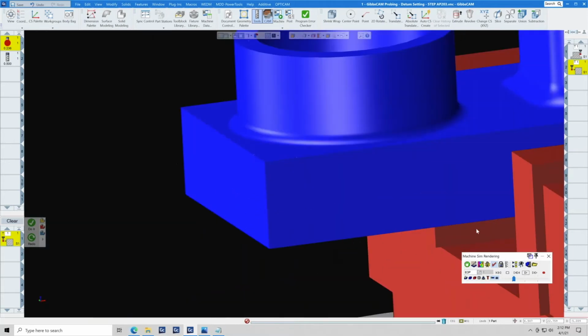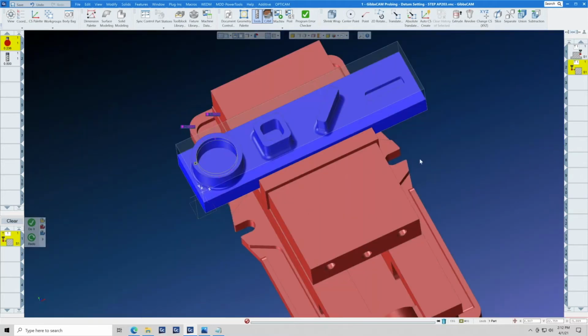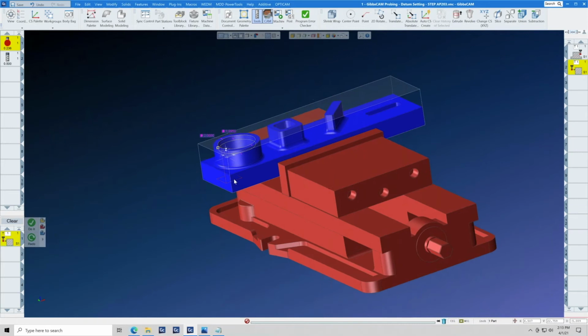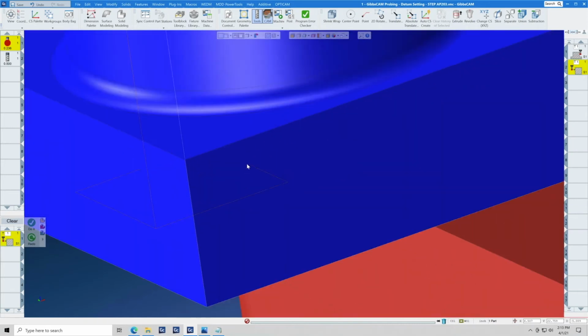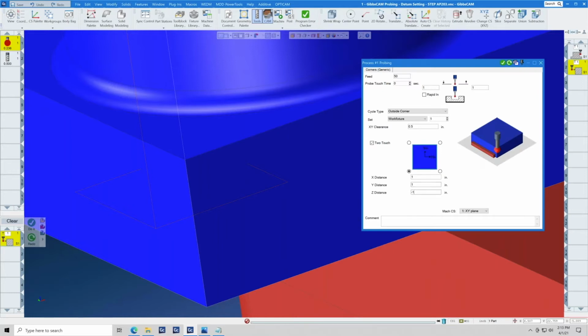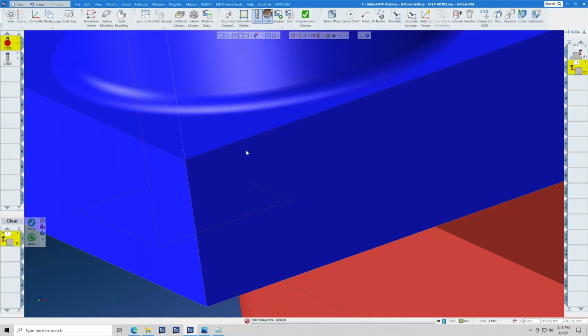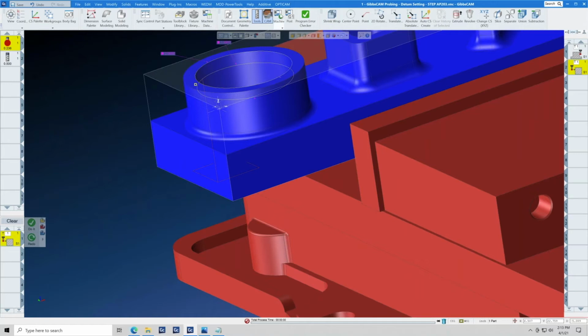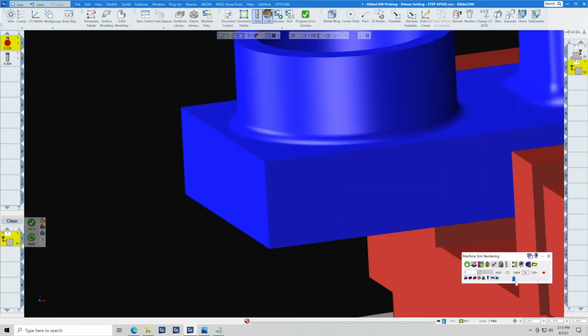Now we need to move that down just a little bit because it put the center line of the probe. It showed us that we made a mistake. So this line is the bottom of the probe. We want to move it down just a little bit, and let's move it down another 1/8 of an inch since we're using a 6mm probe, which is roughly 1/8. I gave it another few thousandths, and we're now at minus 1.125.